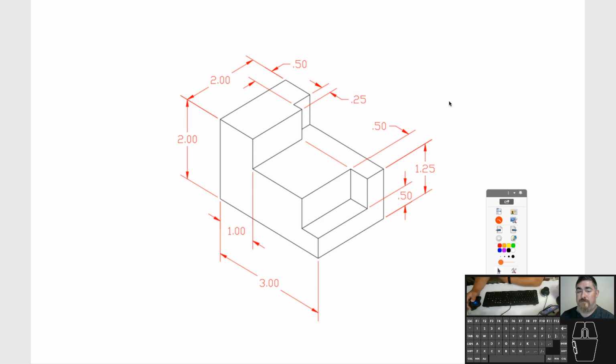So how do we do that? And how are we going to create this? How could I do my sketch? What would I do for my first sketch? I could do just a box and extrude it the full height, or I could do a box and extrude it just to here, and then draw another box and extrude it up. Or I could draw a little L shape, because that's 1, 2, 3, 4, 5, 6 lines. I could draw that and extrude out. So that's the overall shape. So maybe I'll do that.